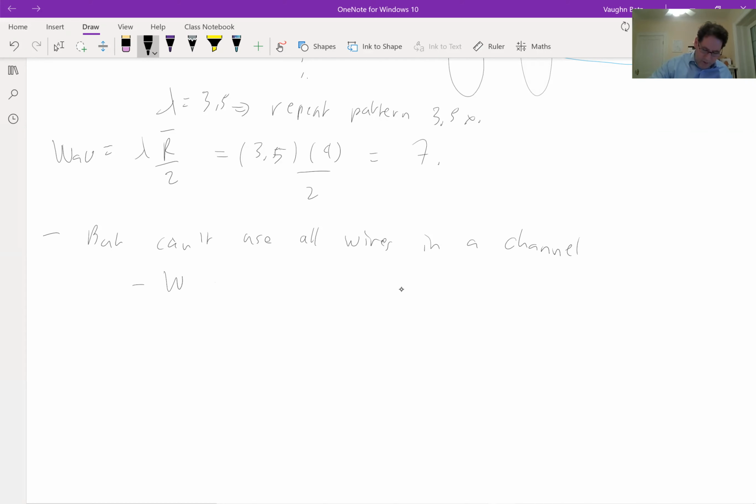So this W is the average number of wires per channel. It's not the peak. And to fail to route, all you need to do is need more wires per channel in one spot than you have, and your router fails. Okay, so we need to actually design for the peak, not for the average. Okay, so there's a few reasons. So we need to architect for the peak.